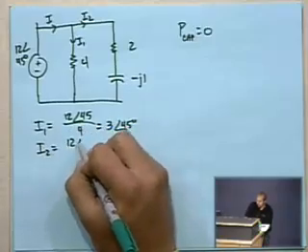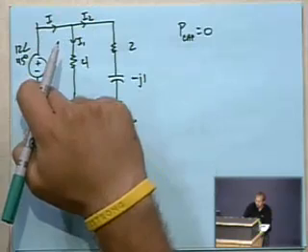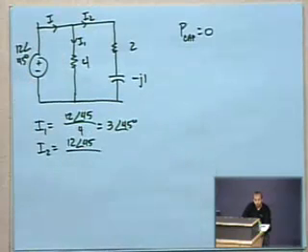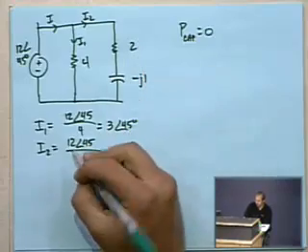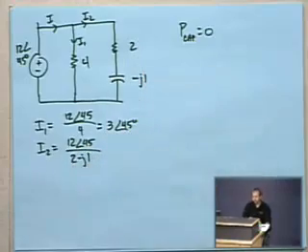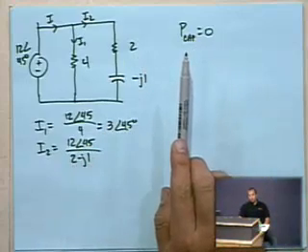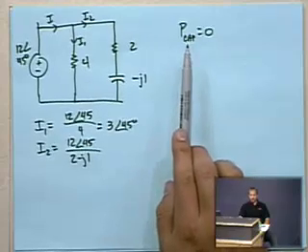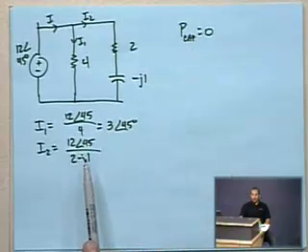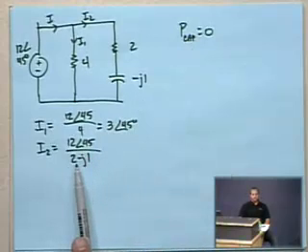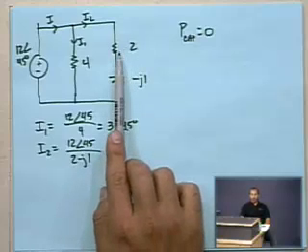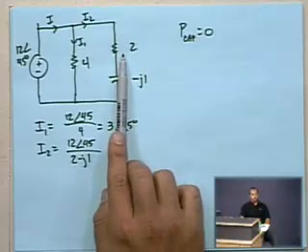It's going to be that same 12 at an angle of 45. Again, it's in parallel with the voltage source. But we have to divide by the total impedance, which is 2 minus J1. So again, the point is that despite the fact that the average power consumed by the capacitor is 0, we can't ignore its influence on the circuit. It still changes the phase angle of at least this branch of the current, which changes the average power that's going to be absorbed by this.